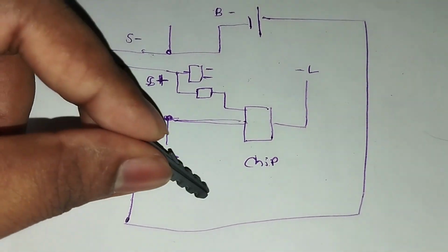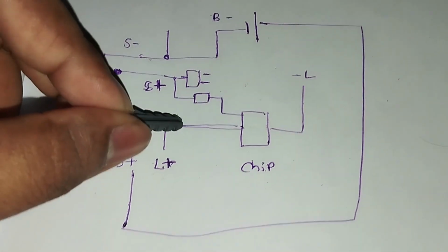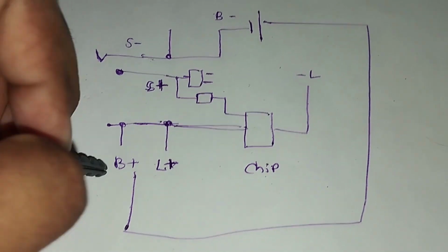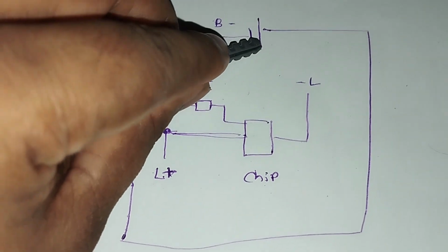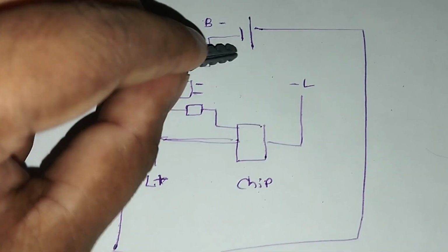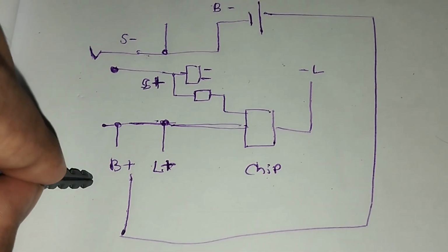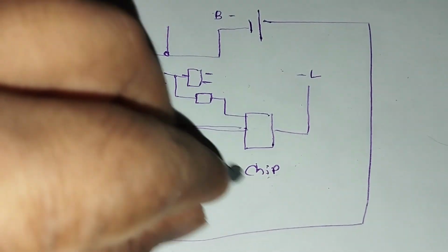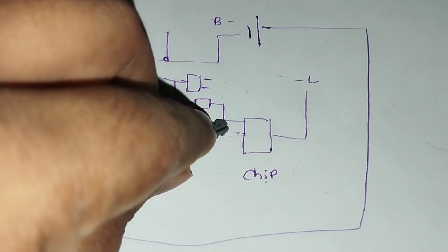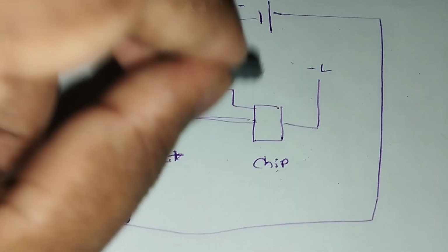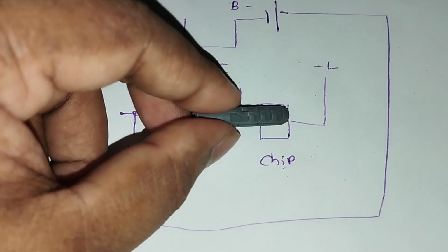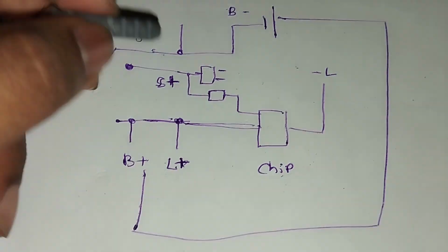According to my simple idea, this just connects the negative of the light panel to this chip. This is definitely switching the lighting from this chip, and the light is switched from the negative side, because the light is always energized if you connect the multimeter, as I have shown, to L plus or directly to the battery, and then to this light negative. You can see a few volts, sometimes up to 2 volts, energizing the light even when it's shut down. That is why we have another draining function mentioned here. It's not there for no reason.